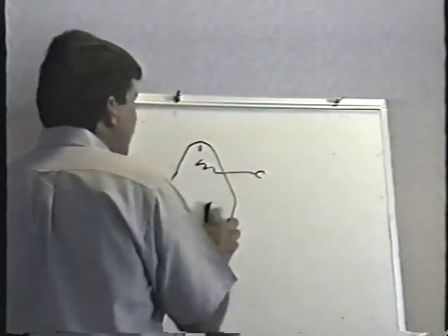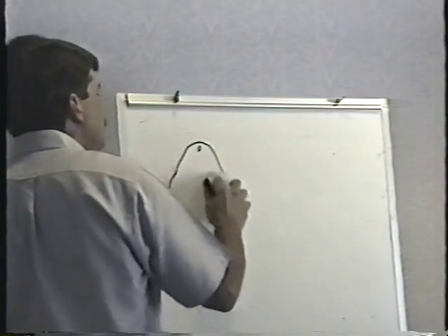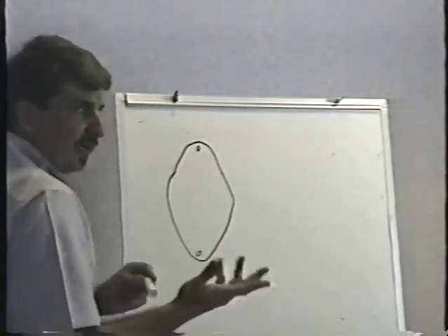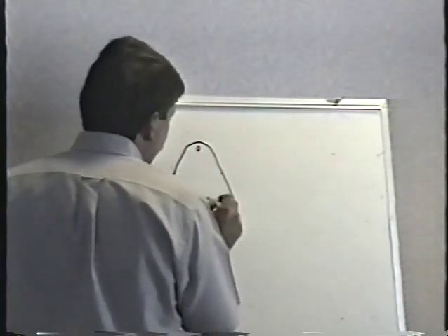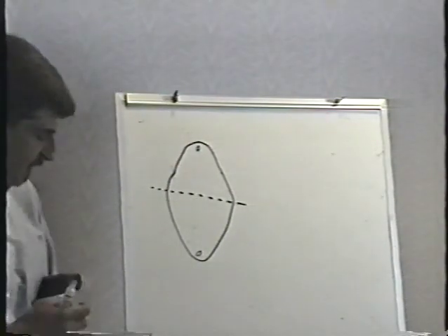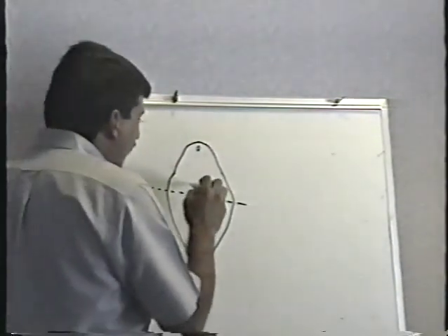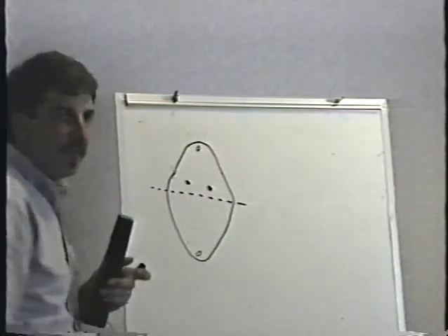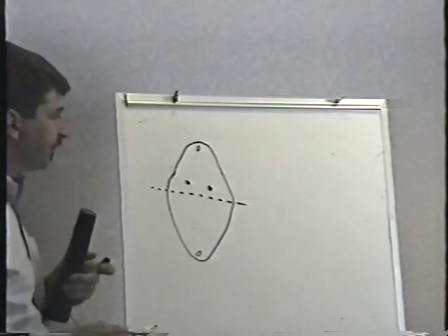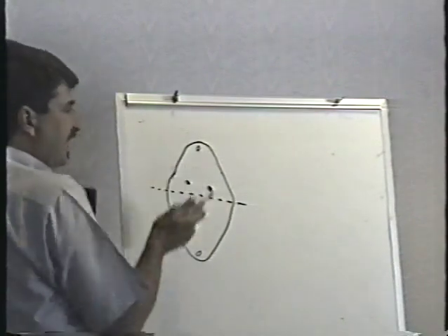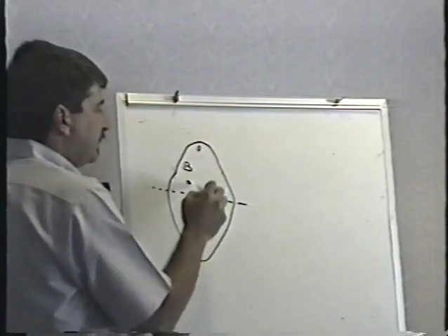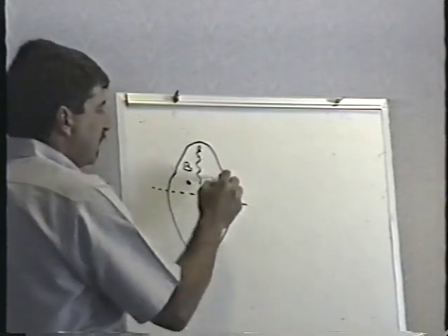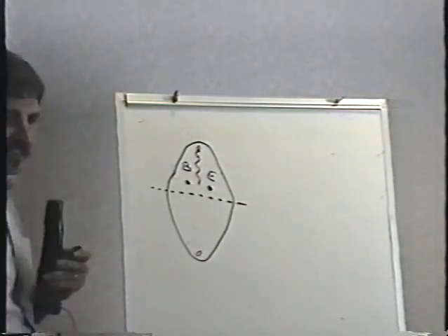Now, even though it's printed like this, the way I normally think of this transistor, because you do have to know which lead is which, is that if you look very carefully, if you draw an imaginary line dead center in that transistor, you'll see that those leads are not right on center. They are slightly offset, aren't they? If you look at it carefully. If I hold the transistor so that the leads are slightly offset above the center line, they're in alphabetical order. Base is on the left, the collector is the case, and the emitter is on the right. That's the way I remember it.